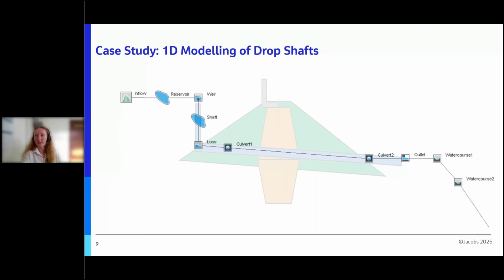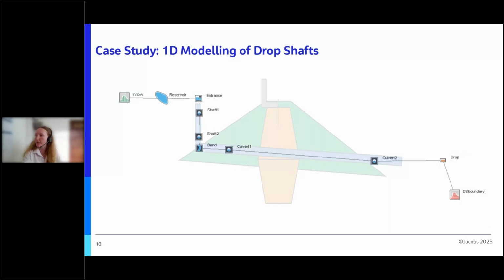So in this first schematic, I've used an outlet unit connecting the culvert with the downstream watercourse. This setup is applicable if the culvert is expected to be drowned and impacted by downstream water levels. Now, if we flip back onto the second schematic, you can see I've terminated the model right at the downstream end of the structure. This is a good option if the outlet is followed by a drop and is falling off into space and isn't going to drown.